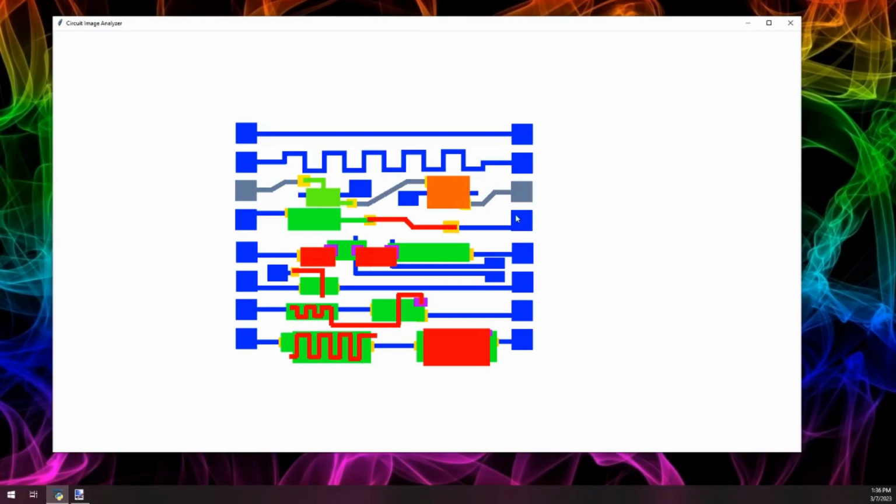And of course, there's other rules involved here. For example, like I said, I don't expect there to be any vias that connect both diffusion and polysilicon together. I would expect that to happen only in the buried layer, but here I've got one test that has diffusion and polysilicon passing over each other with a via underneath, and you can see when you click on one side, it only selects that one side or the other. It doesn't select both because they're not connected. So it recognizes that there's no connections there.